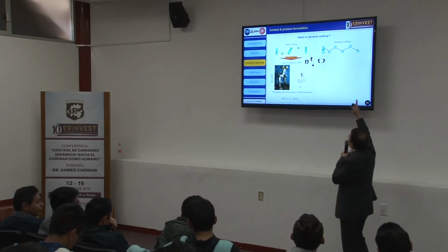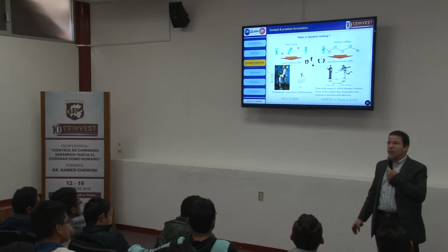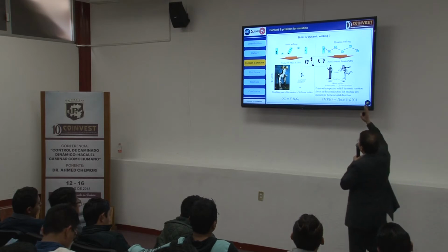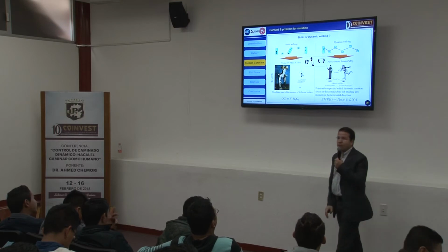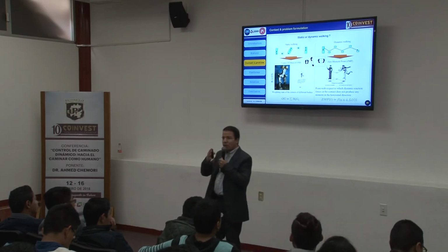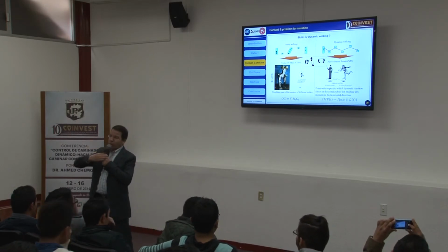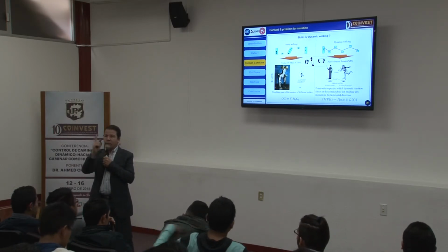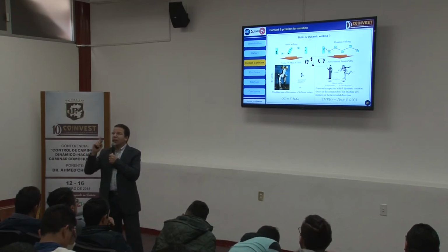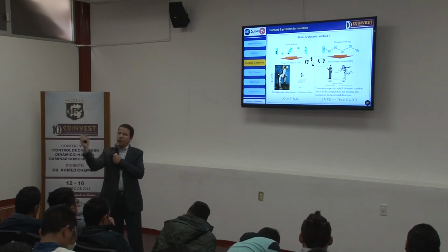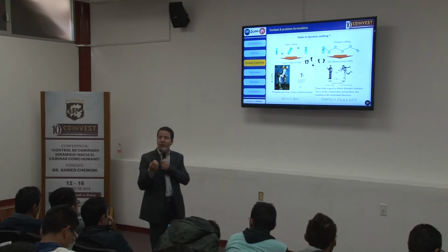Now, for dynamic walking, we will not use the center of mass. We use another concept, and this is the concept introduced by Miomir Vukobratović in 1969. It's called the ZMP. ZMP comes from zero moment point, and to understand it is very easy. If you have a body in contact with another body, you compute the vertical contact forces with the ground, and you compute the resultant, the big force that includes all the forces. Its position represents the position of the ZMP.